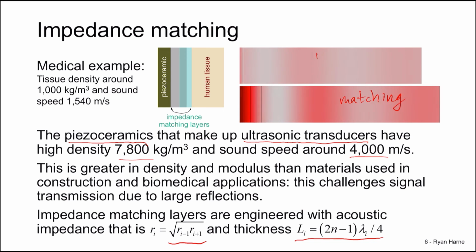The simulation at top does not have impedance matching layers. The piezoceramic is directly applied to the tissue. At bottom, several impedance matching layers gradually reduce the impedance from the piezoceramic quantities down to human tissue to enhance the acoustic power transfer.